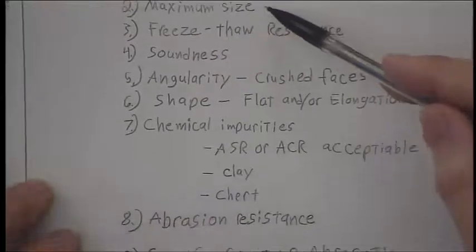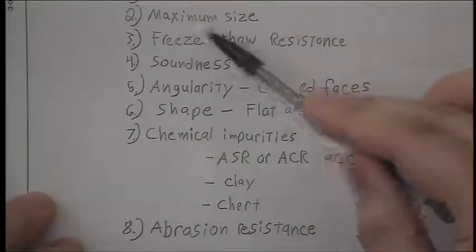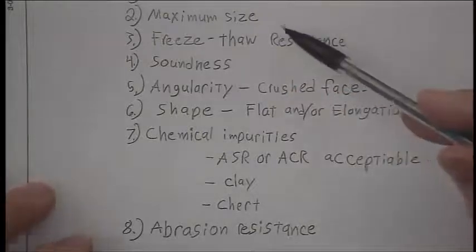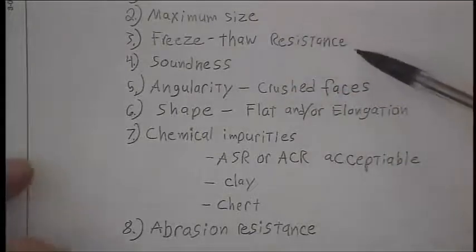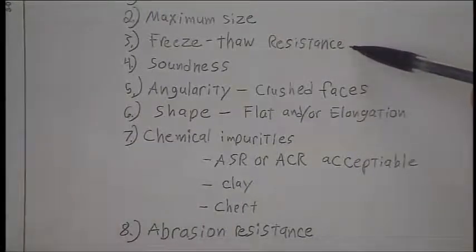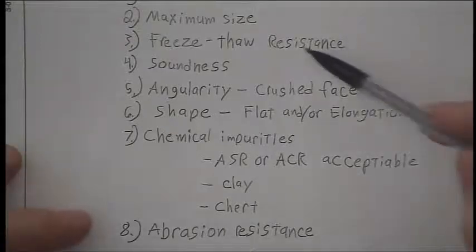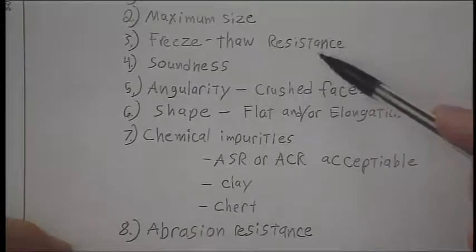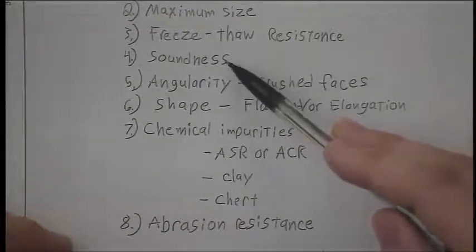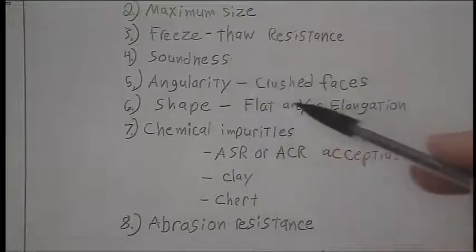Typically you have some type of maximum size, where you don't want to get too big in a certain range. Especially for concrete, you want it to be freeze-thaw resistant. For riprap and drainage conditions, you also want it to be freeze-thaw resistant. You don't want too much soundness issue, so volume change.